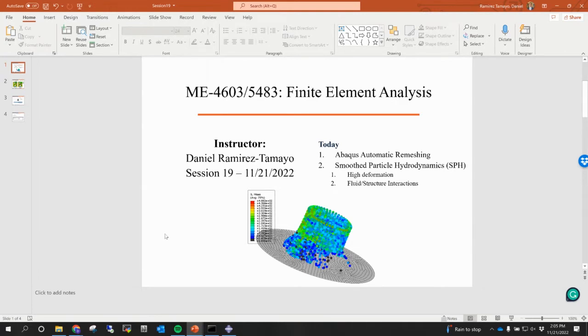So for example, there's a tutorial that if you search about this method online, you're gonna see a propeller impacting with a bird, and then how the bird damages the propeller. That's something that is seen a lot, right? How do we model the bird? Just a sphere or a cylindrical shape with some properties of meat.